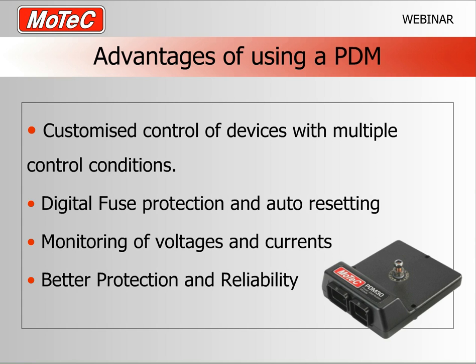Secondly, the device itself operates like a digital fuse for each of the outputs, and that means that multiple conditions can be set, and this will allow fail-safe operation in a racing situation where a normal fuse would simply trip out and disable the car.